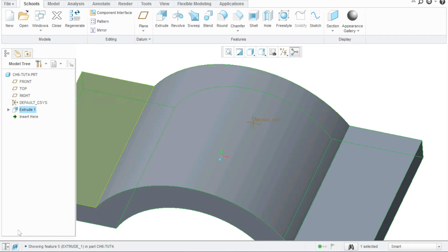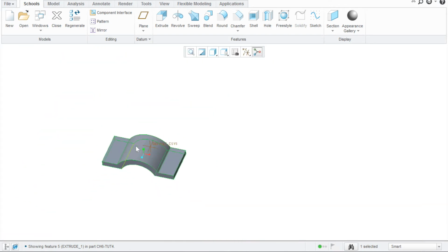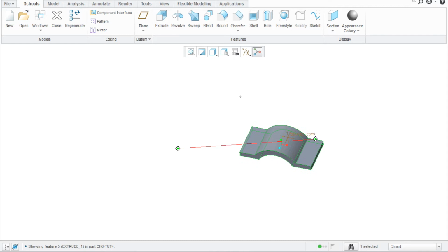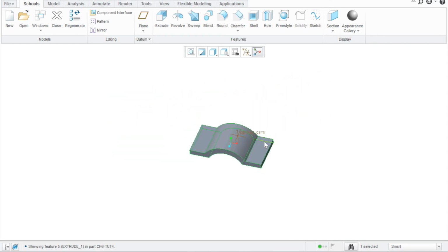Now we go to extrude number 2, and that is we click on shift and middle click. You can move them around, okay? So you can relocate the part. And if you lift your finger from the shift and then try to rotate, you can rotate that.